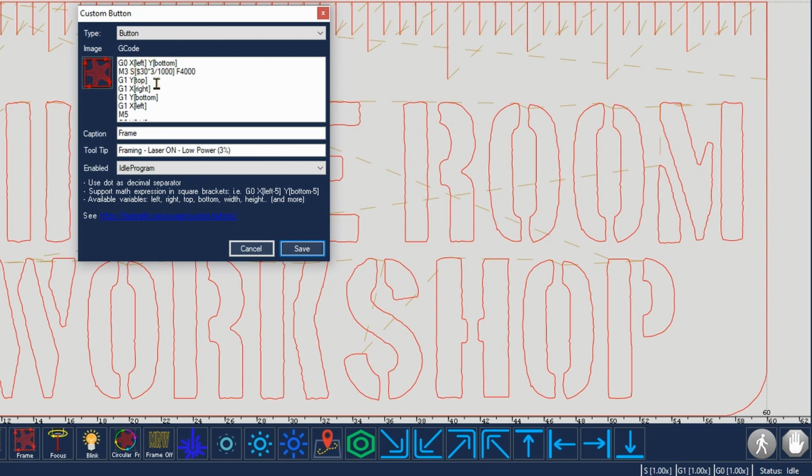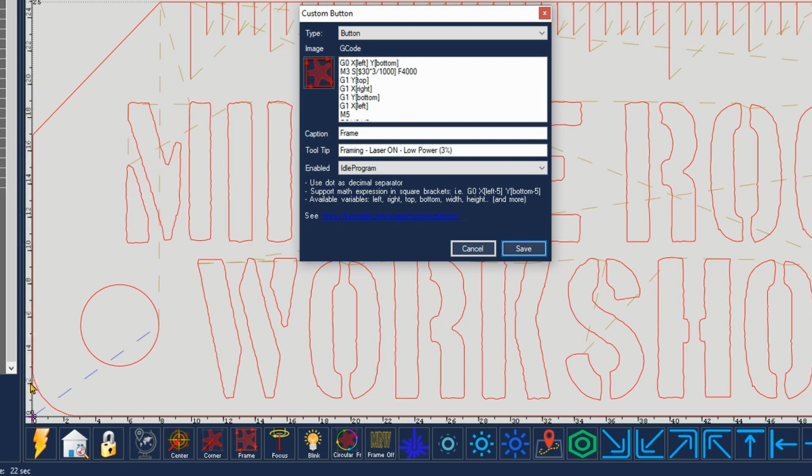And this is actually fairly simple. Now, these X and Y's are basically referring to the actual project which is loaded in the canvas. As you can see over here is this keychain from my channel. And so when you say, for example, X left, that means move the X axis to the left of the project that is currently loaded. So this will basically move the X axis all the way to the left of the bounding box, so the rectangle that encompasses the entire project within it.